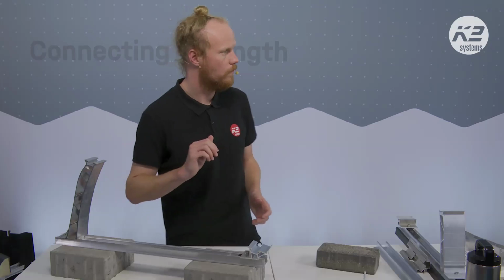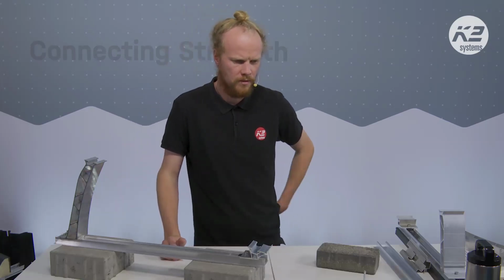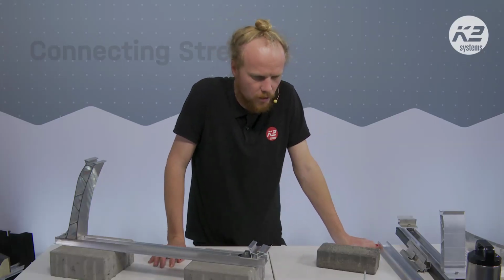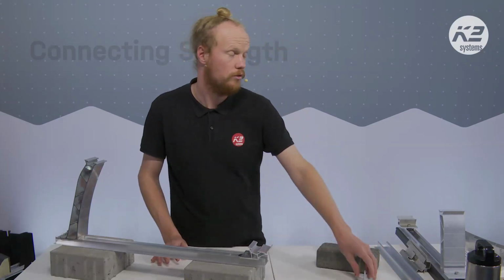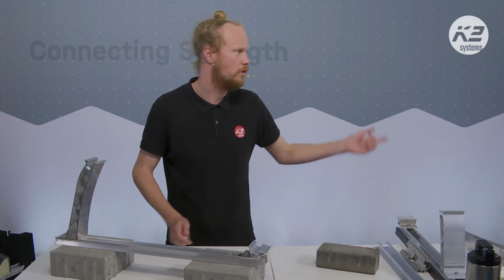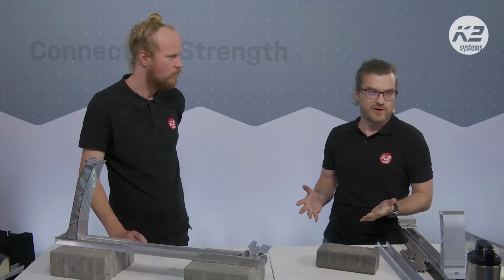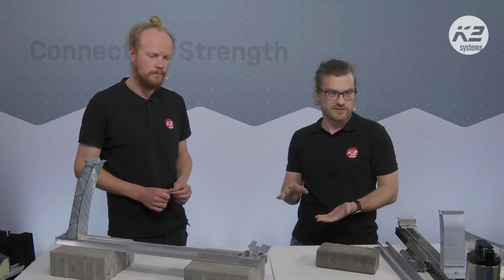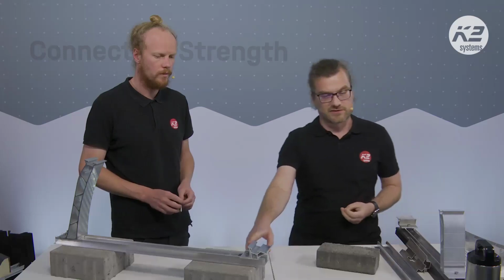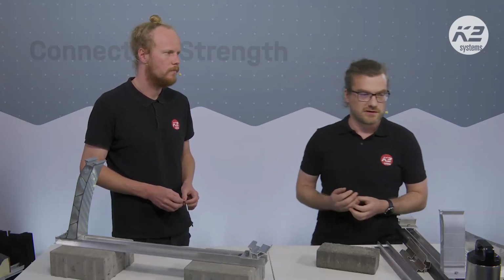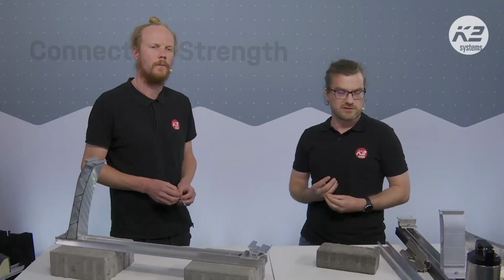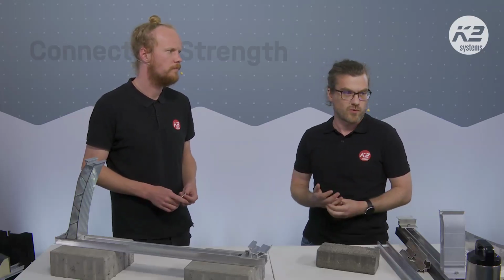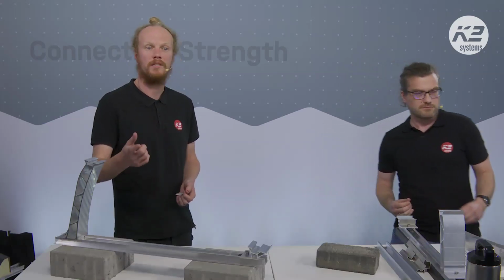Karen, we have some good questions. Yeah, for example, about technical requirements for our concrete blocks. With the concrete blocks, yeah, it's a good question. From our side there are no requirements about this concrete. It's only the weight, so you have to calculate it in base and put the correct weight, and the maximum height of the stone is 25 centimeters, and not higher, because our system was tested until this height and no more. And that is something that you'll see in base as well.